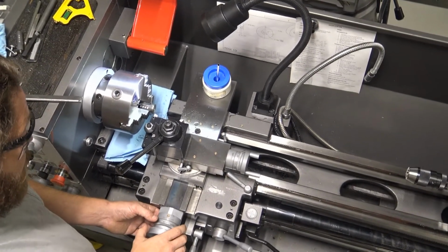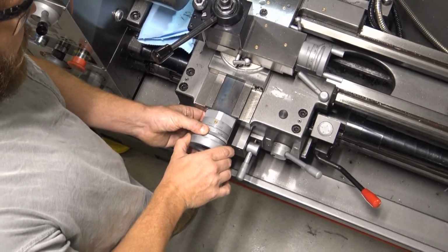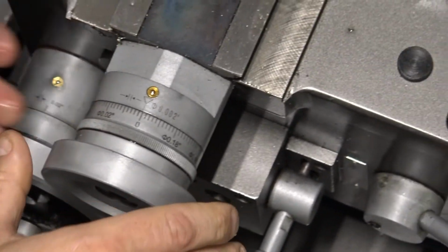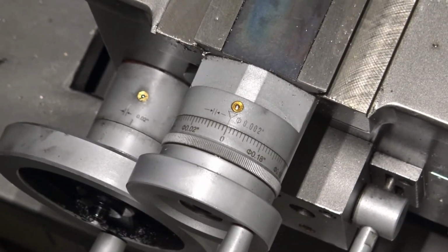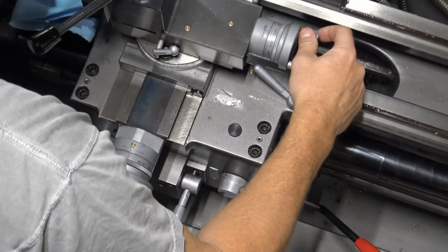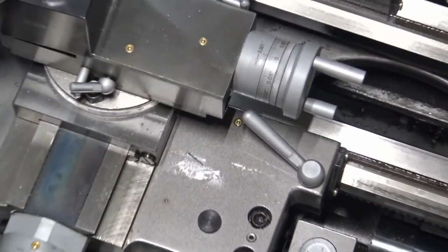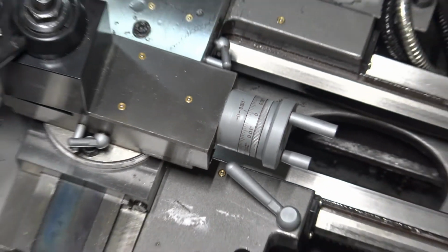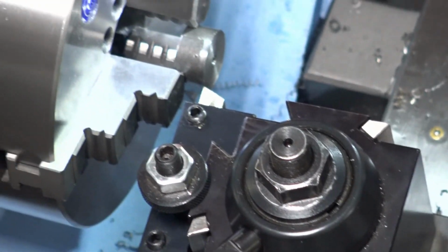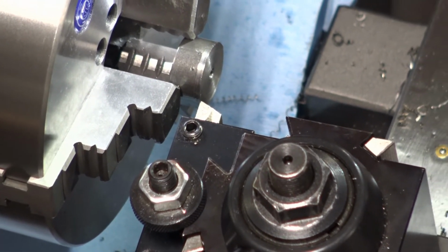All right. So down here on my cross slide, I want to set this to 0. That's going to represent the outside diameter is at 0. If I move this back to the 0 right here, it's going to be hard for you to see, but the tip of this tool is right at the tip of the part, right on the edge, where the outside diameter and the face of that part come together. So now we're all set up and we've established a good origin.